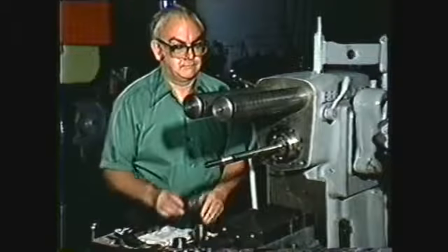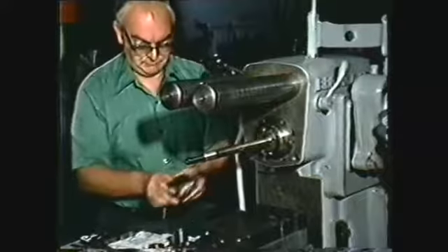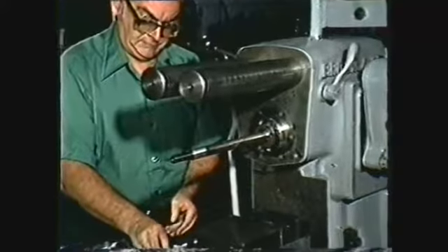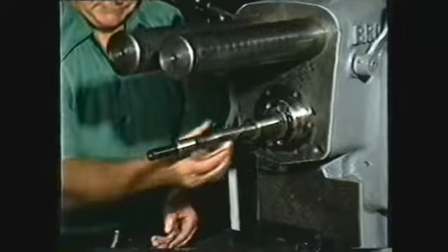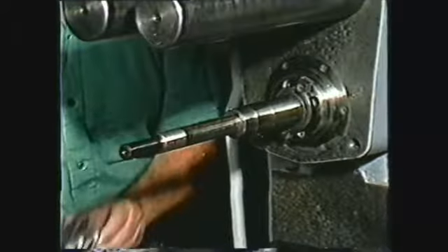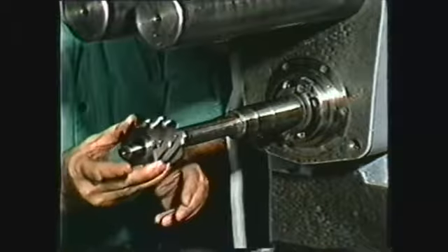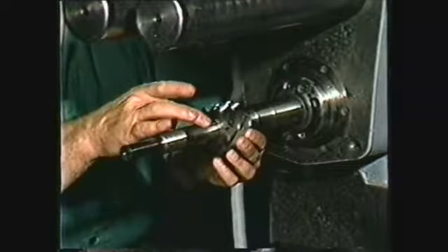To provide the most rigid setup, the cutter should be located as close to the column as the workpiece will permit. Place collars on the arbor so that the cutter can be positioned over the work. Then place the cutter so that it will rotate in the direction for conventional milling. Secure the cutter in place by sliding it over the key in the arbor.